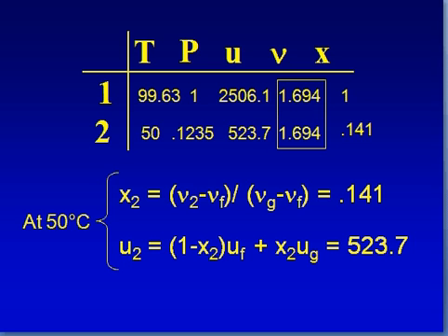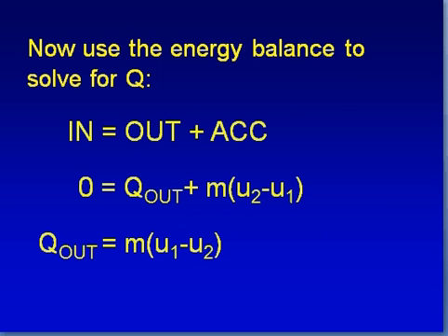Given that V1 equals V2, you can use information from V1 and T, and you'll find out that it's a saturated mixture. You go about using the volume and the temperature to calculate the quality, and these are things that we've done in the first few weeks of this course. U, you can calculate from the quality. Once you calculate the quality, U comes up to 523. So now we know we have the table completely filled out and we can answer questions related to this problem.